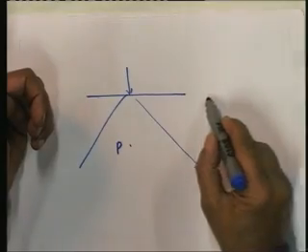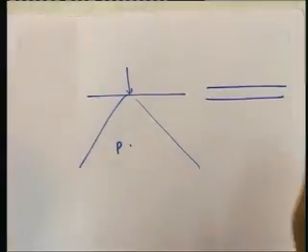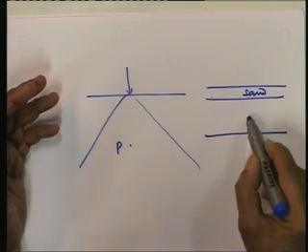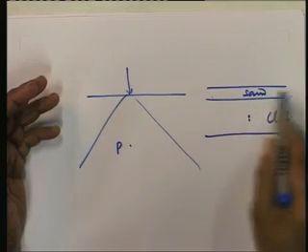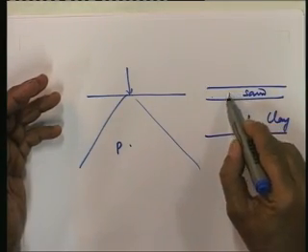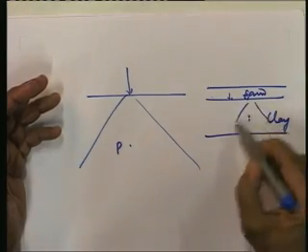But here, since the layer is uniform and is of a very large extent, the sand layer for example, at mid depth of the clay layer, whatever stress arises due to this sand layer, we take as equal to the weight of the sand layer itself without accounting for any reduction due to dispersion.